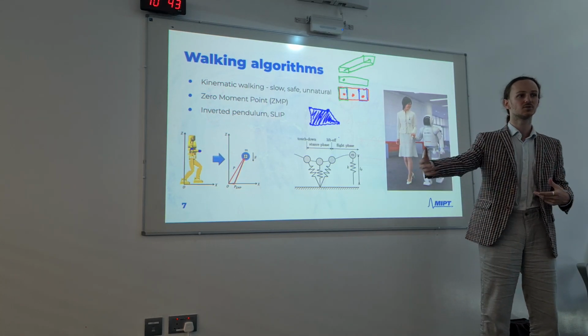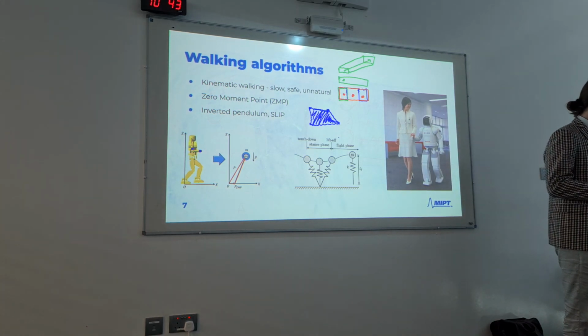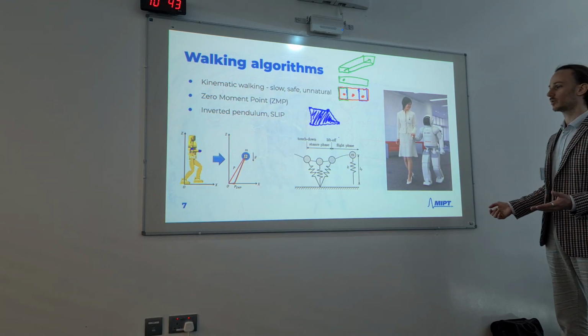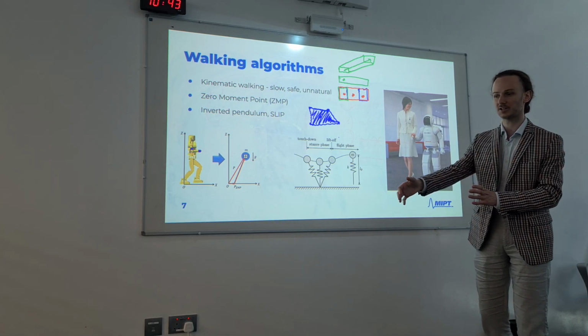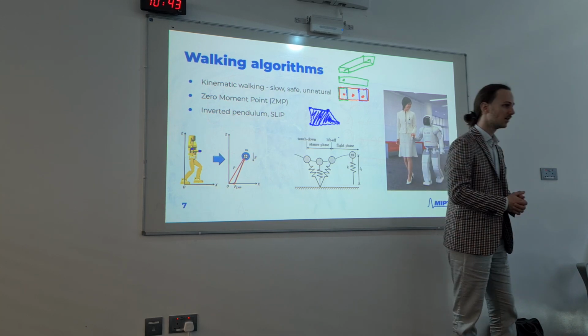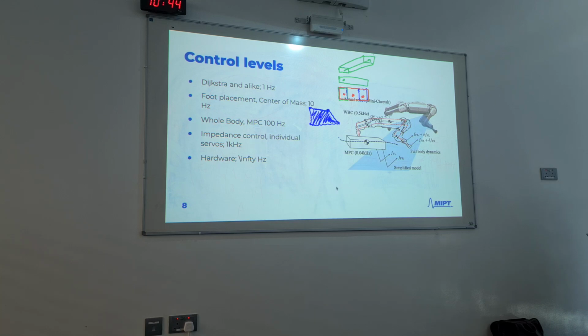Of course, the model is not precise, and there are noises and everything, delays, but it is indeed possible, and this is one of the common ways to make robots walk. So we use some kind of simplified model, generate the trajectory, and then try to follow this plan. This is what is commonly going on in the humanoids and quadrupeds. There are several control layers actually.